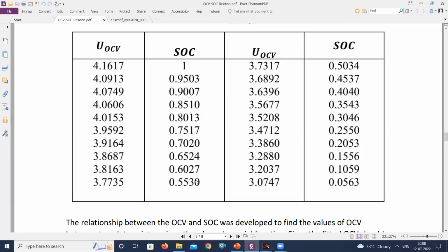So the manufacturer specifies their nominal voltage, and whenever you procure a new cell, just test the cells from the lot to see whether the voltage is up to that level or not. If the voltage is higher or if the voltage is low, don't accept that cell at all.